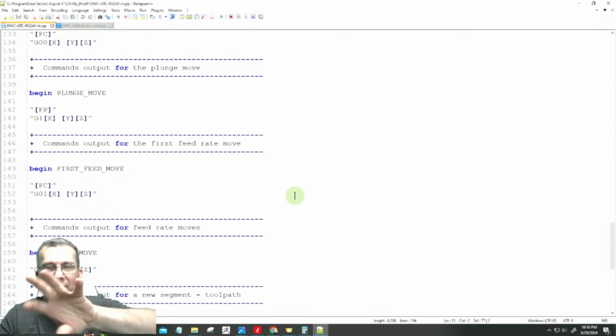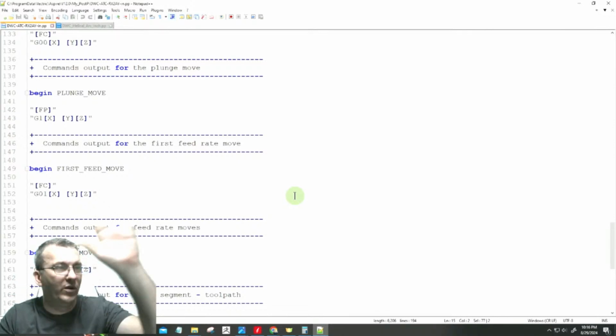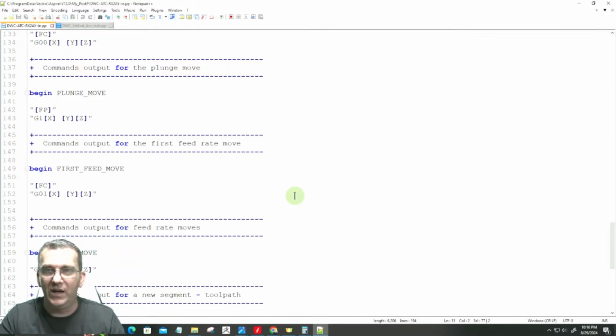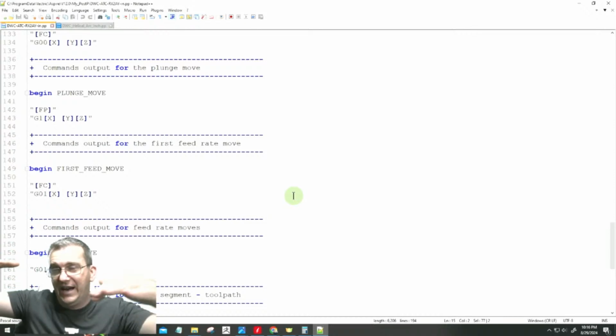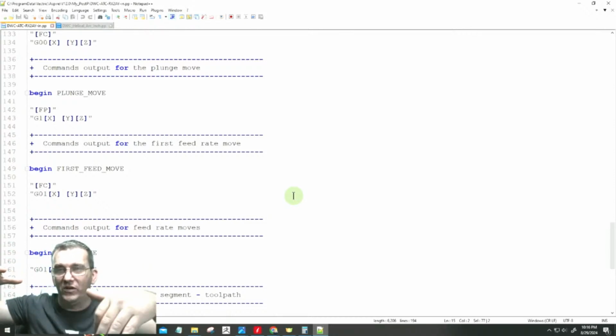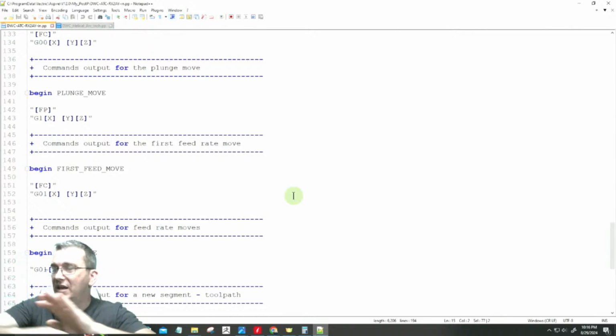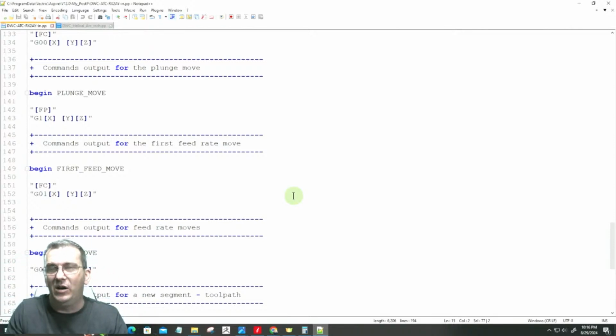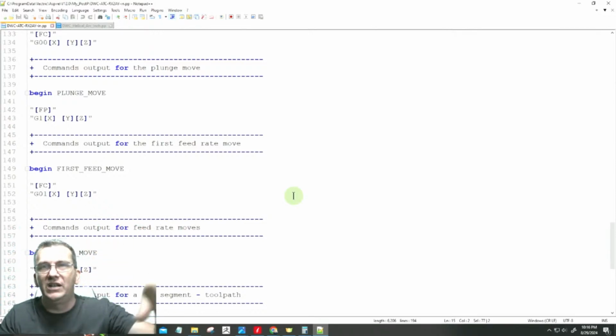That's 0 to 360 degrees, the turning. You will not see a Y-axis whatsoever in that G code. And if your fourth axis is turned the other way on the table, where it's running along the Y and the X is the rotation, there will be no X-axis outputs in the G code. It'll only be Y, Z, and A. So it takes all those X values and converts them to A automatically,